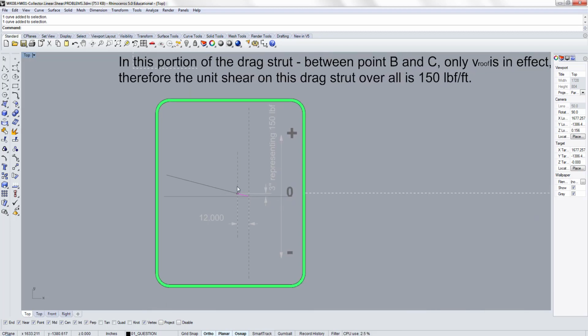What scale you use here doesn't matter too much. There are two things you need to be careful of. One is, once you pick that scale, you should be consistent throughout the problem, because if you change the scale, then the graph reads differently. You can pick whatever scale, but you have to stick to it. Second, the scale has to be reasonable so that you can draw this diagram within a readable portion.